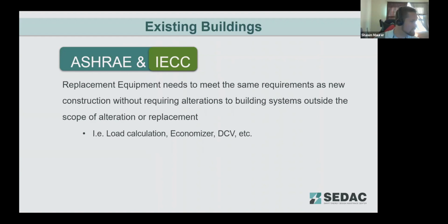And then we had a question about, I believe, the unoccupied standby. Is that a requirement and not an option, correct? It is one of the prescriptive requirements in ASHRAE. So if you're following that prescriptive path, then yes, it would be a requirement for those spaces. It is not a mandatory requirement though, so it doesn't have to be done if you're doing one of the other performance paths.